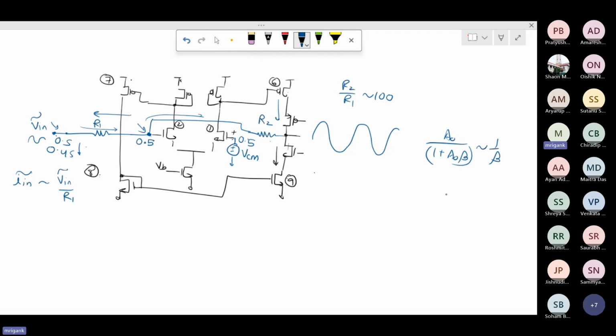Negative feedback, what happens, right? In negative feedback, if you have a very high gain amplifier, all throughout you have been studying that in a negative feedback voltage follower, how does the voltage follower work? Ultimately, if you have an ideal op amp, we say that these two points will always be the same. Whatever VDC you apply, it will appear here as VDC. Why does it appear? Because of the negative feedback.